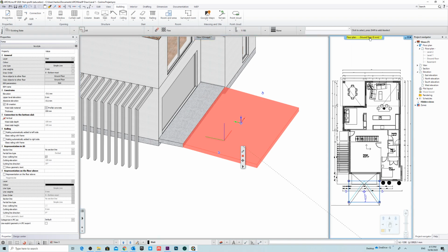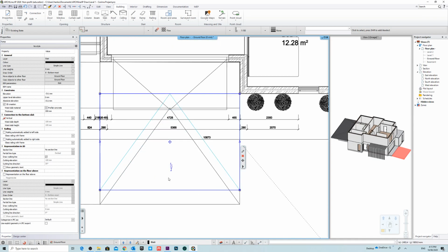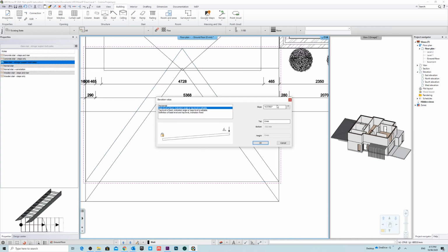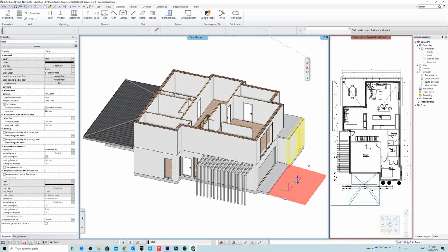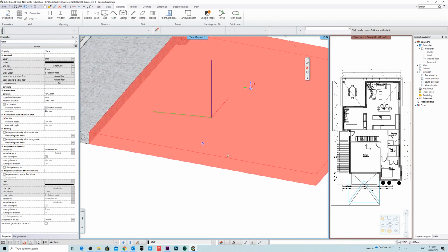Okay, so we're just going to go check out the slope, and we can just change base is fixed, inclination angle, top angle. Okay, definition of base, inclination is fixed. Base level is fixed. Top level is fixed. Okay, top level is fixed. So we can just change the slope and we'll make it 5 degrees, just a little slope. And we'll go back. Okay, so I think that should be fine.